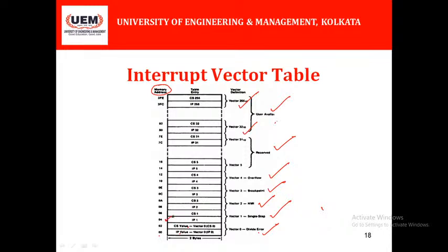For example, address 04, meaning 00004, stores IP1, that is the instruction pointer for vector 1, the single step interrupt, and address 06 stores the code segment register value for the single step interrupt. In this way, NMI, breakpoint, overflow, reserved and user available interrupts are all calculated.